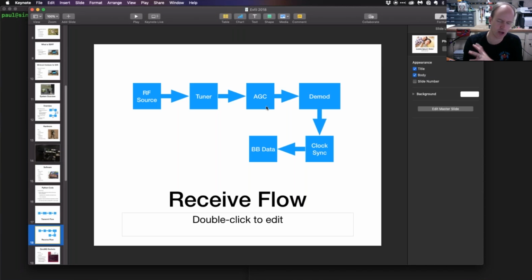Because I supported on-off keying, and if anyone has questions about this I can do a deeper dive, when you're dealing with frequency based systems, you have to worry about your frequency tuning, but you don't have to worry about your amplitude as much in general. On-off keying systems, you always have to pay some attention to what the amplitude is and make a judgment call about when it's high enough that you're going to interpret it as a 1 and when it's low enough that you're going to interpret it as a 0. And unfortunately, in an OOK system, if you just move it further apart, the signal gets weaker. And so the discrimination between the 1s and the 0s starts to get more complicated or more arbitrary.